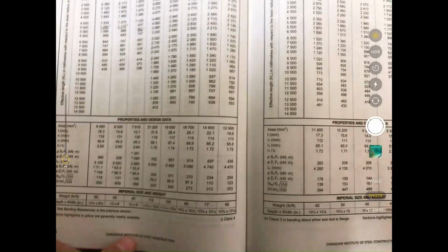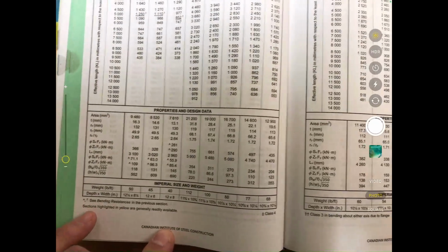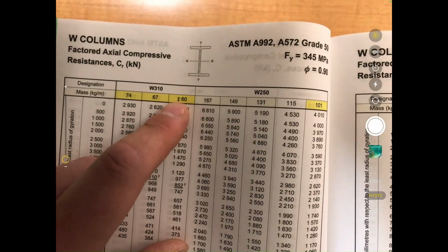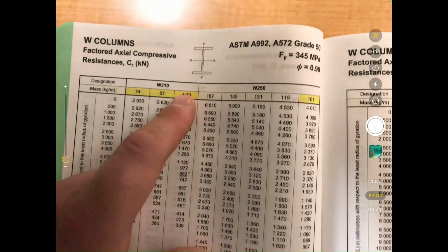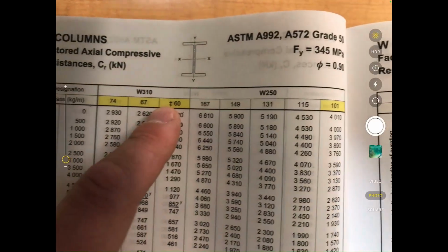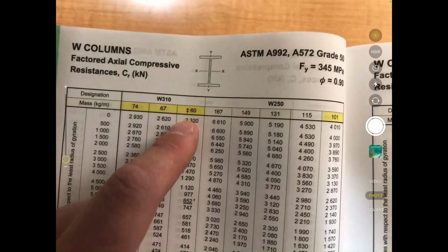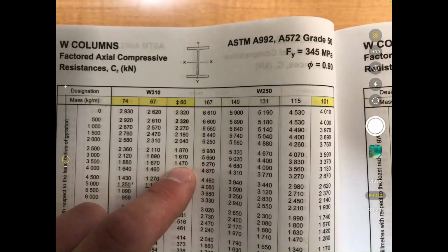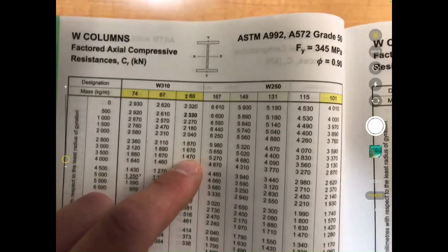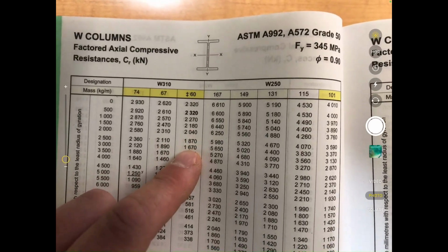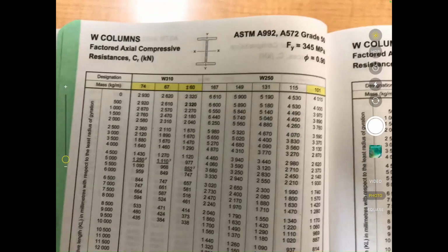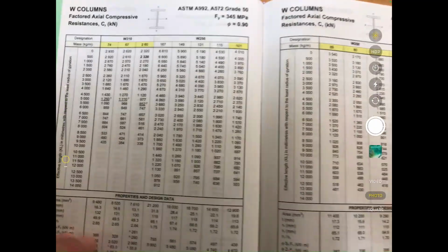Well, from time to time, it's going to hit something. Where is that? Sometimes there'll be little sections like this that have a little dash. Normally, that section means that it's class 4, and the handbook is already going to state the effective area for you. So local buckling is already included in these compressive resistance values. Picking something from this table means that local buckling has already been considered in the strength as well.